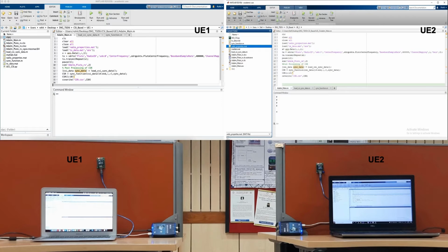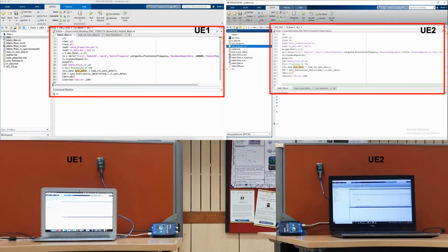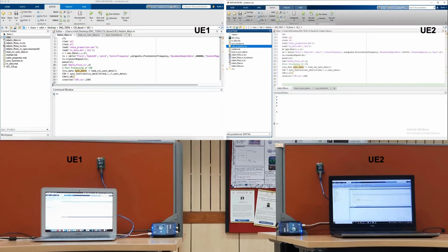Setup is as follows. UE1 and UE2 are willing to generate a key using correlated soft channel from ADALM-Pluto hardware. We have used this MATLAB code to trigger the channel and then estimate the received vectors. As these radios and host systems are not synchronized, we operate them in full duplex mode instead of operating them in time division duplex manner. We choose adjacent correlated frequency bands for full duplex operation.